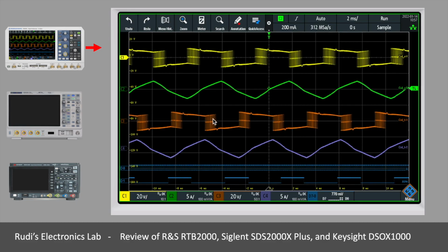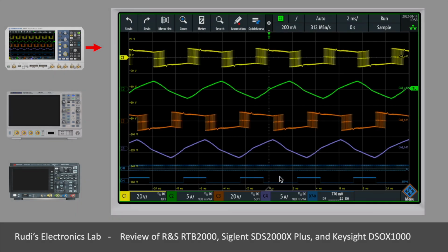And then we get to see the same thing for the other coil of the motor, both the voltage and the current that is flowing through it. I also see the two digital channels. They're not in sync, at least not the last one here, with the signals I'm looking at, but actually I have them here because I want to be able to measure their frequencies and understand the relationship between the pulse control and the final rotation speed of the motor. And I'll turn to that measurement in a little moment.